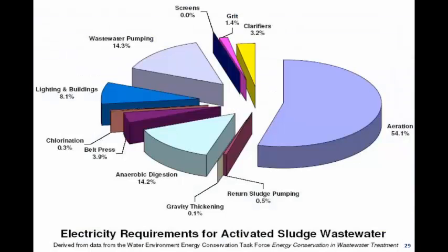So as you can see here, and Dr. Galinsky mentioned this, which was great, there's a huge relationship between nutrient control and energy management, very synergistic. Aeration clearly represents the single greatest energy demand within most wastewater treatment plants, namely activated sludge plants. Over-aeration to some extent is common, it's wasteful, it's costly.